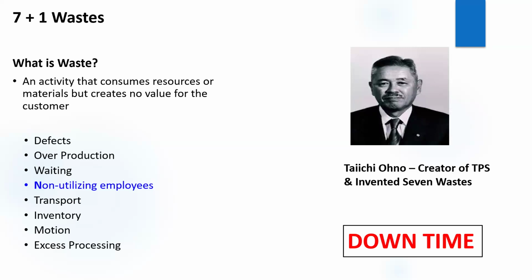I'm assuming that there's a customer order. You are not overproducing. Suppose you have a customer order and as soon as you receive the material, please process it as early as possible. And it is said that single piece flow is always desirable, because as early as possible we are moving this material from our workstation to the next workstation.